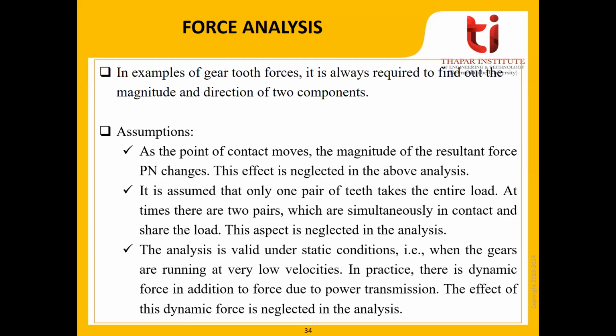The analysis is valid under the static condition. That means when the gears are running at very low velocity. In practice, there is a dynamic force in addition to the force due to power transmission. So in the coming time, we are going to discuss the dynamic effect also while we are designing the spur gear.